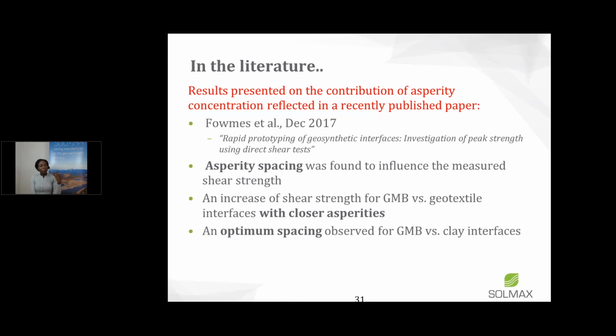So when I was looking at putting the webinar together, I found that there's a recent paper on the contribution of asperity concentration to interface shear resistance. The paper was just published in December 2017. What they found was that asperity spacing had an influence on the measured shear strength, and that in contact with geotextiles, when you have closer asperities, you can increase your shear strength.